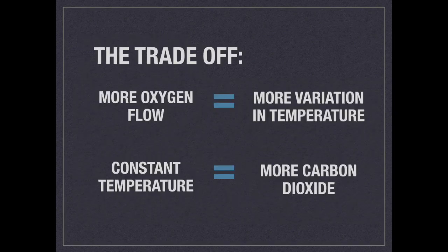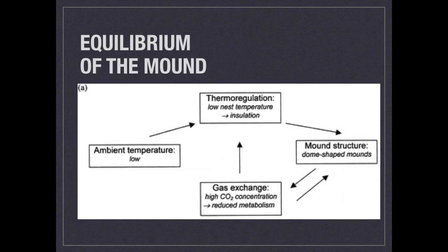The mounds must balance the level of ventilation with the temperature of the mound in order to allow for fungus growth. These mounds breathe similar to a lung in the way that they take in oxygenated fresh air from the lower holes of the mound and exhale CO2-rich air from the chimney and upper holes. The air that leaves the central chimney is generally warmer than the air that is being drawn into the mound from the lower holes. The ground temperature continues to keep the nest cool.